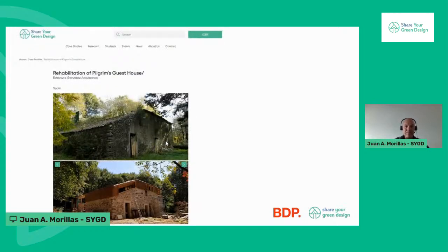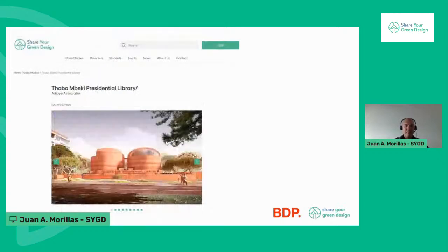This is another very sustainable way of construction, which is retrofitting existing, old and derelict buildings, because they are already there, and the building that emits less carbon is the one that already exists. It doesn't have to be old and derelict buildings. They could be buildings built in the 70s, the 80s, or even the 90s that, for some reason, don't serve the purpose they were built for, and then we can retrofit them and change their use as well.